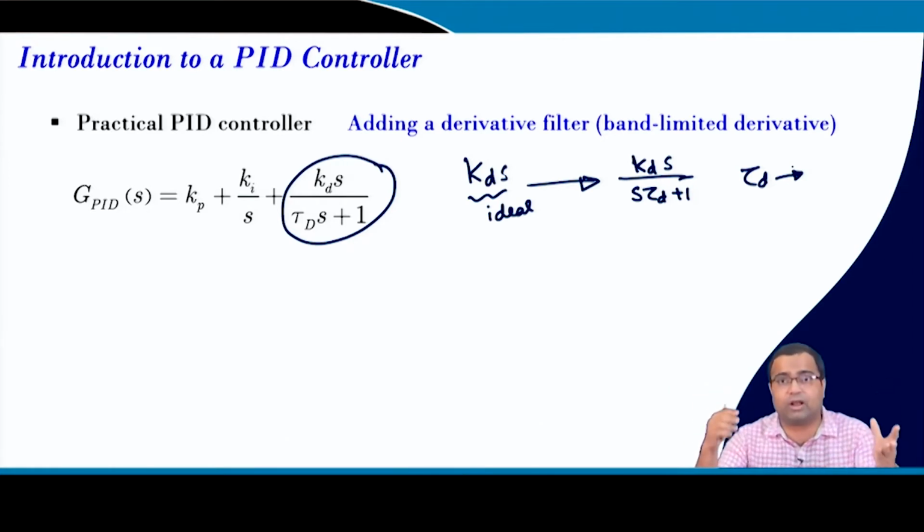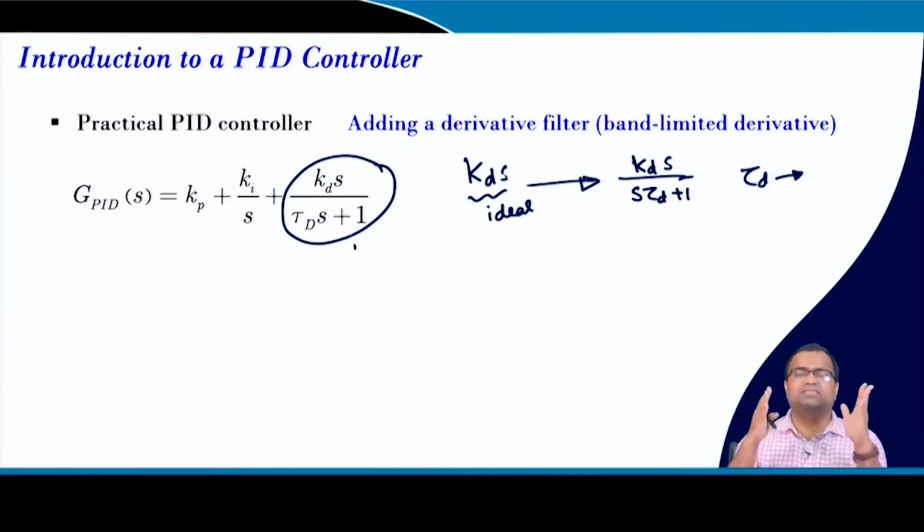Whenever you are talking about, let us say, a 1 megahertz converter, we take some hundreds of megahertz op-amp as an error amplifier. As a result, the op-amp bandwidth is pretty large, but sometimes we may not even want such a high bandwidth for the derivative filter, because we need to attenuate certain switching noise. In that case, we may want to increase tau d slightly.